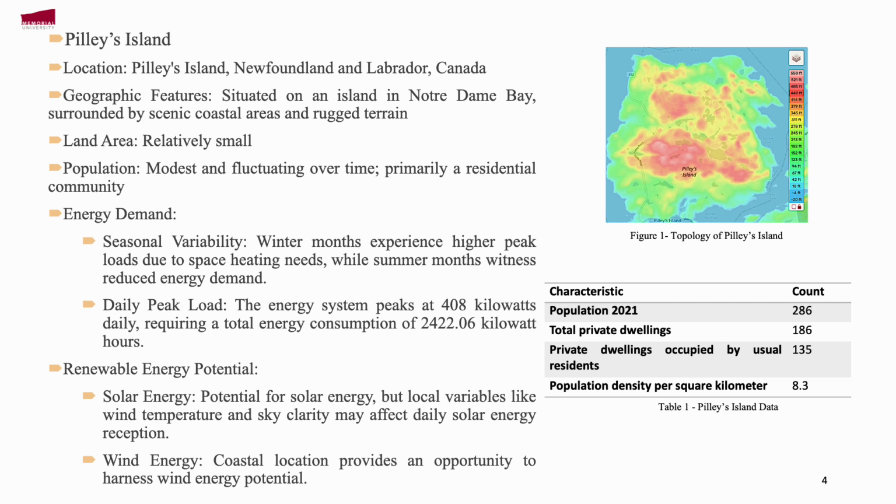The energy demand varies seasonally. Winter months experience higher peak loads due to space heating needs, while summer months witness reduced energy demand. The total average daily consumption is about 2500 kilowatt hours, and after researching a lot, the renewable energy sources really suited for this island are solar energy and wind energy.